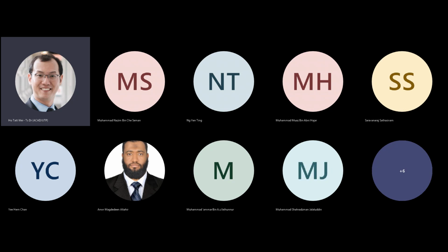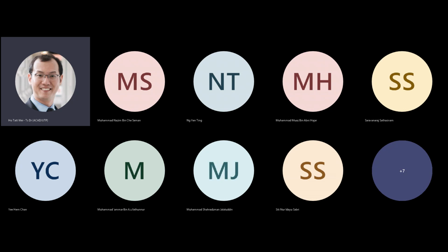So this is what a switch network looks like, such that if this switch is closed and this switch is open, okay, so if I close this switch, this output here is tied to VDD. Okay, this is a logic 1, so VDD can be 1.1 volts, 1.8 volts. It depends on whatever technology you are using. And if you were to then use the voltage to open this switch, and then you end up shutting this switch, the output is then connected to ground, so it's logic 0 here.